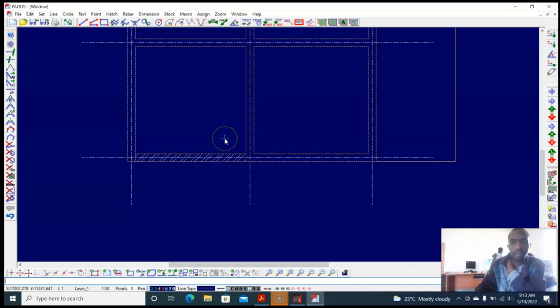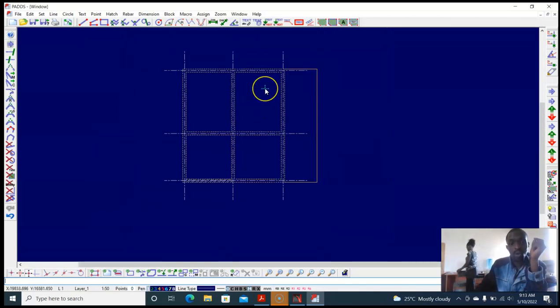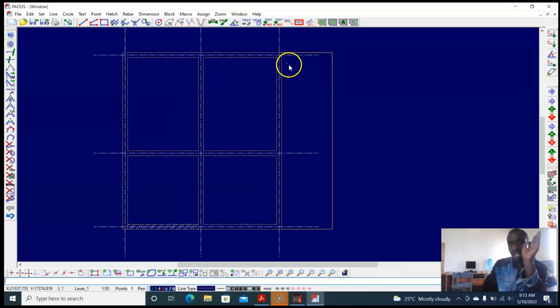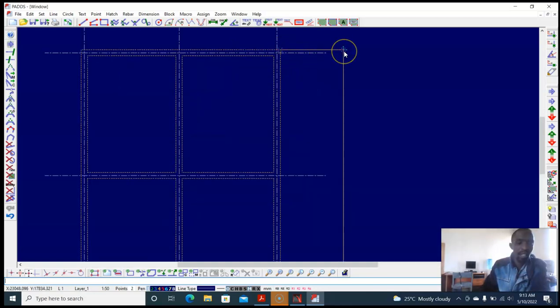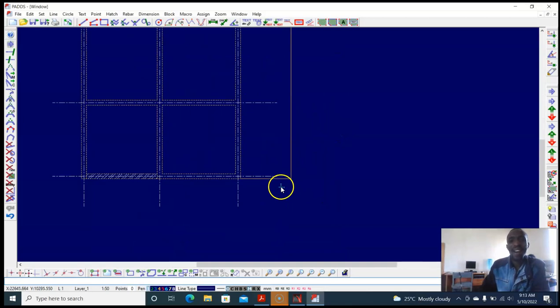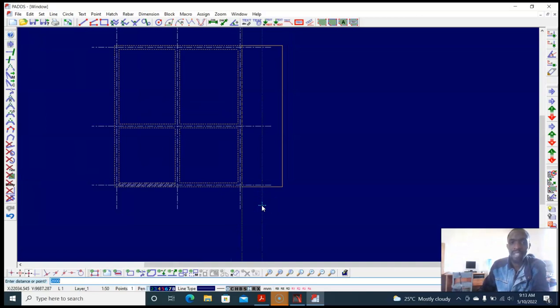So at that place the slab is going to behave differently. Let's start with an assumption. It's just a cut. There's no beam around, it's just a plate. Just the slab, no beam around it. And 2 meters is too much for a single plate. 1.5 is okay, let's do 1500. Otherwise, you would need a beam around there and here and there. So let's do 1500.